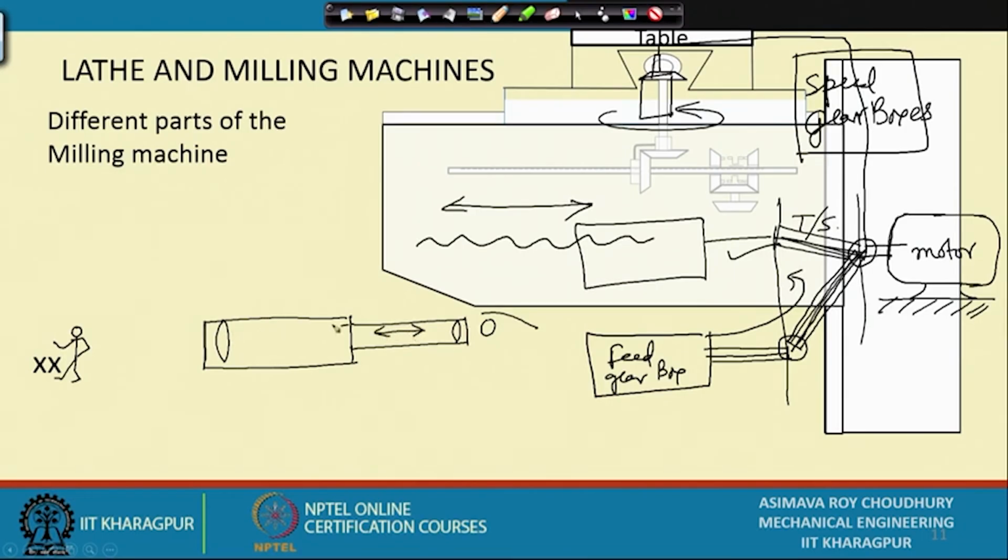How is it movable? Maybe it is provided with a jacket. This is a sleeve and this is movable inside this sleeve. The same thing has to be done here, and that is why it derives its name telescopic shaft. But if you give a rotation to this, if there is nothing to stop the rotation, this side will rotate. Let me rub it out and actually draw a telescopic sort of link.